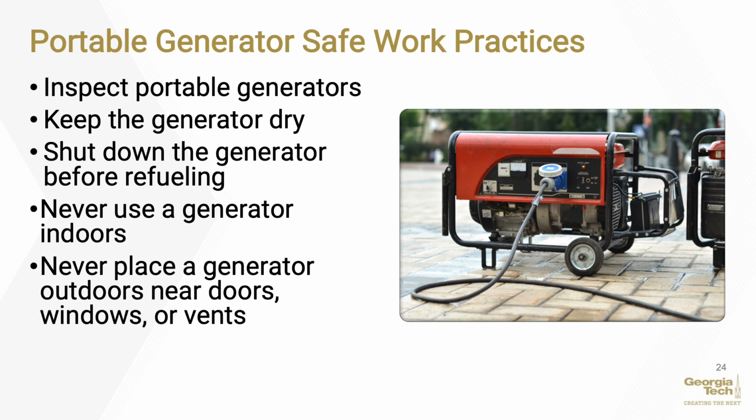Always plug electrical appliances directly into the generator using the manufacturer's supplied cords. Use undamaged heavy-duty extension cords that are grounded or three-pronged. Use ground fault circuit interrupters, GFCIs, as per the manufacturer's instructions. Before refueling, shut down the generator. Never store fuel indoors. Never use a generator indoors.